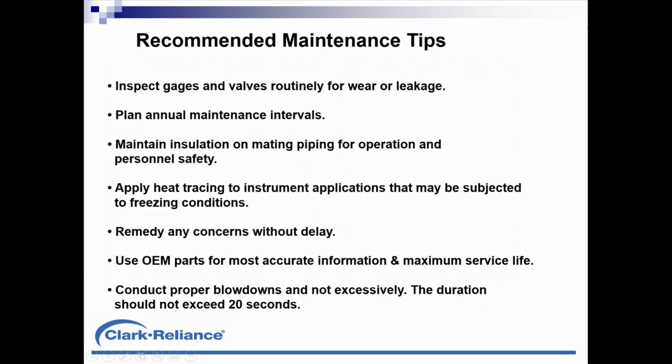Inspect your gauges and valves routinely for wear or leakage. Plan annual maintenance intervals on these devices. Maintain insulation on the mating piping for operation and personnel safety. I cited that insulation on that drain piping earlier.